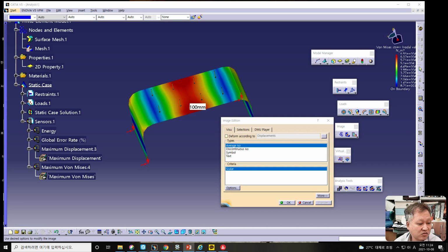And the result of the shell element can also show stress for upper, lower, and mid positions. A 3D element can be displayed using a cut plane anywhere inside the shape. In general, structure failure occurs at the surface, so the stress inside the shape does not significantly affect the analysis of the result.